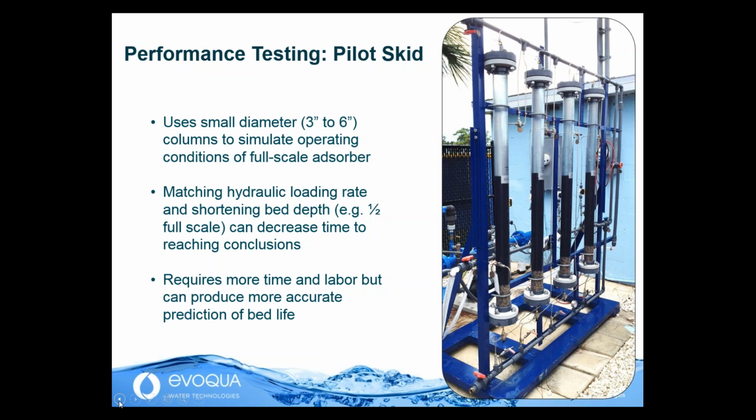We can accelerate this test to some extent by running a shortened bed depth, but by matching the hydraulic loading rate. But in general, I would expect somewhere between 6 and perhaps as long as 9 to 12 months of runtime before we're going to see breakthrough and have a useful result.